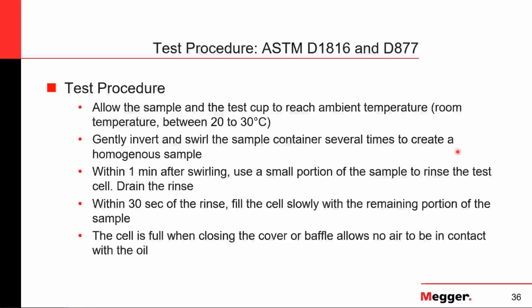Fill the vessel up to the level indicated in the vessel itself, and then proceed to place the cover or the baffle in a way that no air is in contact with the actual oil. Of course, this part of the procedure applies for both D1816 and D877.